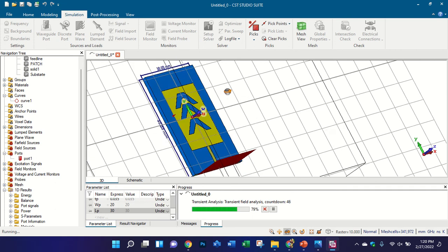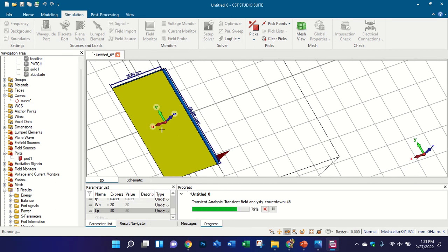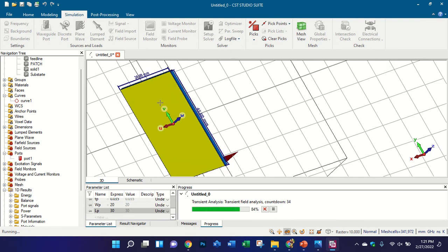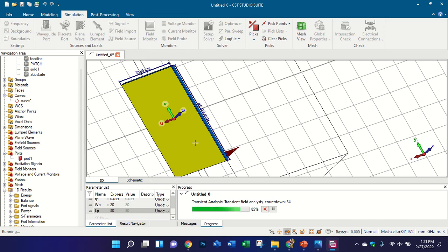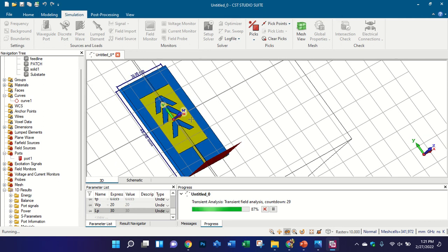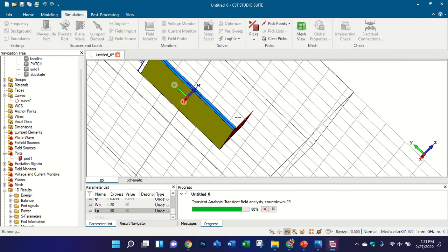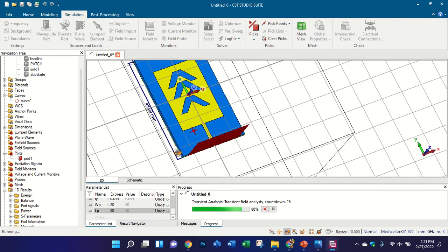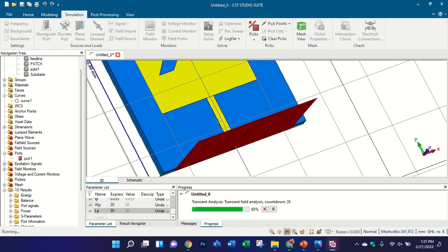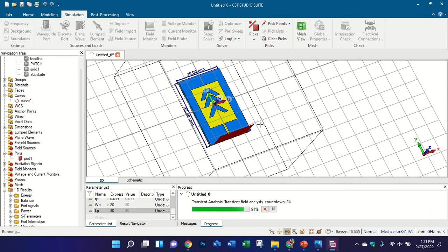And the other thing is that I am using a full ground plane. If you also have slots in the ground plane, then it will become multi-band. It is not necessary to use the full ground plane. You can use a half ground plane, a partial ground plane, modify the shape of the ground plane, or use the CPW plane. I will show you how to design a CPW antenna. This is the simple patch antenna, and you can use the ground plane on this side, the left or right side. In most CPW antennas you can get wide bandwidth, like ultra wide band or wide band, like this.